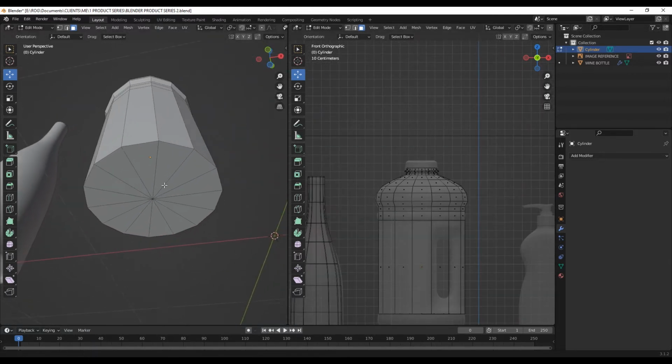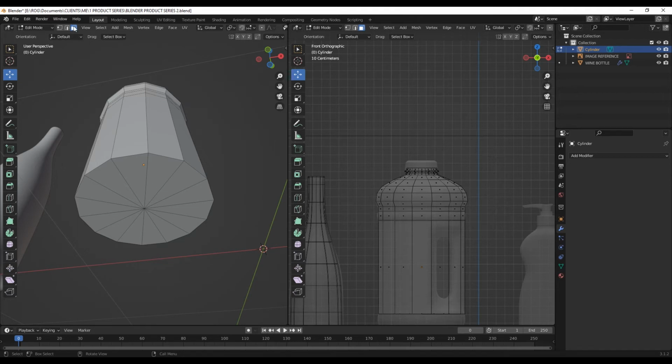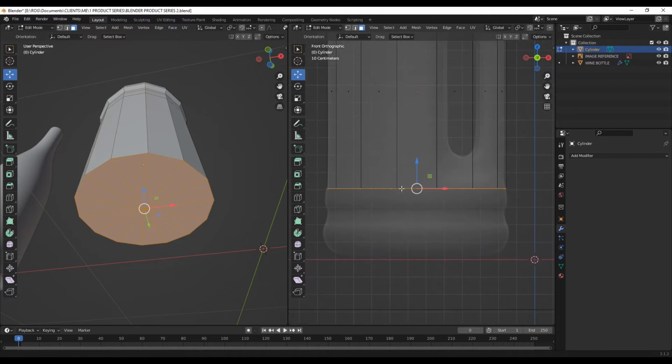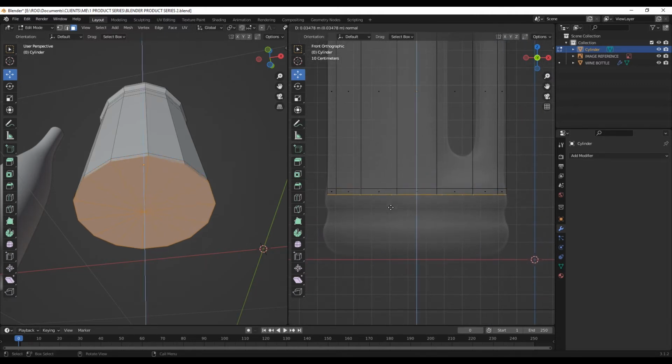So let's come now to select these faces. Make sure you're in your face mode. Then I'll hit C again to bring our circular selection tool. Then I'll just click here at this point, then right click to take the tool away. So let's frame this properly here. So I'll hit E to extrude again, bring this down to this point.